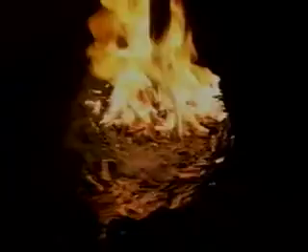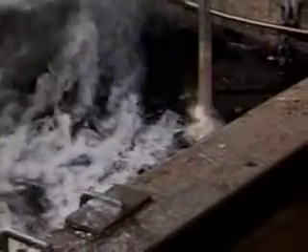The quenching process has long been known as the black hole of heat treating for very practical reason. You cannot see what is happening during the quench once the parts are loaded into the tank. However, once the parts are removed, you may see severely distorted or cracked parts, or you may obtain parts that are too soft or perhaps even non-uniform or spotty hardness. What causes these conditions? Let's first look at what happens when hot metal is immersed into cold water.